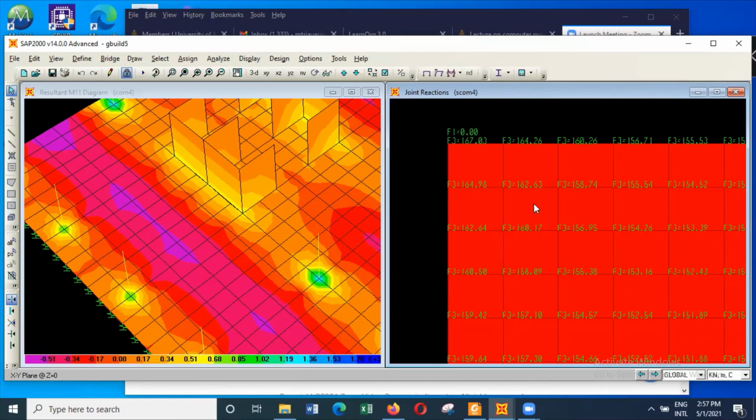And so we consider that the soil has a bearing capacity of 150, and the actual stress is in the range of 128, 130, and so on. So basically, the structure will be safe because we did not consider the weight of the raft. So to the reactions, we'll have to add, or have we considered the weight of the raft? Yes, the weight of the raft also has been considered, because the raft was defined by using normal concrete. So actually weight of the raft is also added.